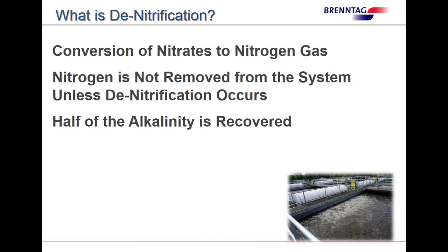This will give me a quick chance to talk about bubbles coming up in your wastewater, your biological system. Great big bubbles are carbon dioxide, and little bitty sizzling bubbles are nitrogen. So if you're getting the real sizzly little bubbles coming up, that means denitrification is probably occurring. The big bubbles, they're still okay. Doesn't hurt anything. It's just a lot of carbon dioxide being let off by the system.